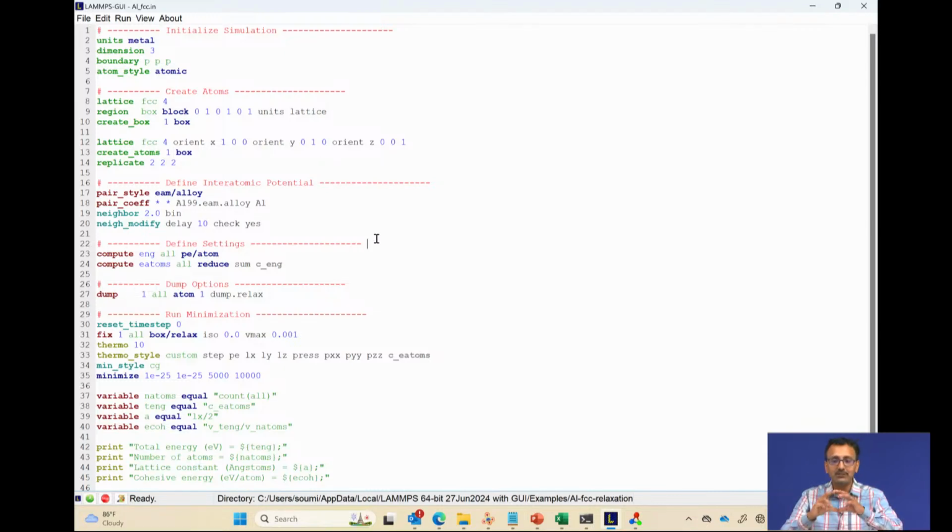Basically, how much you want an atom to move to trigger the need to look at the neighbor list and update it. Unfortunately I can't bring up LAMMPS, but if you just search for LAMMPS neighbor, you will see a very good description of this. The manual is really good. It will bring up all the details of how this works.